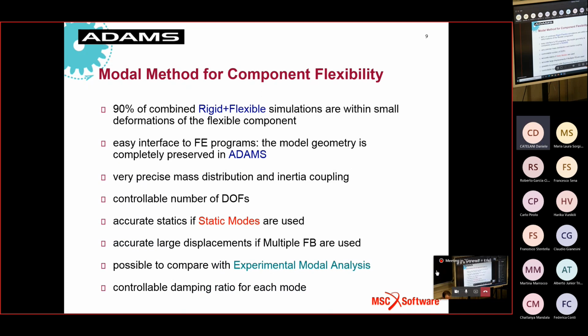What is the reason for using modal flexibility? Because in many applications, the deformation is small and can be considered in the linear range. So the modal analysis is enough to describe the flexibility. The second reason is that when you ask a finite element user, a finite element analyst, to run a modal analysis to create a file for Adams, the activity is easy, is simple. There is nothing strange for him.